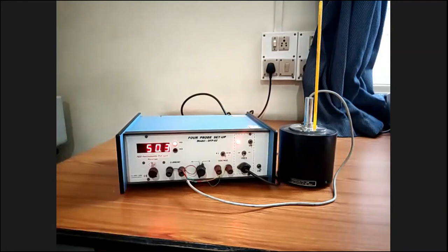And this process is continuously running. Then when the next temperature comes to 40 degrees Celsius, again note down the voltage. When it comes to 45, again note down the voltage. So you have to continue up to 140 degrees Celsius. First the interval will be 5 degrees Celsius, and after 65, the interval is 10 degrees. So you have to continue up to 140 degrees Celsius, and for each and every case, you have to note down the voltage. So this is the process.